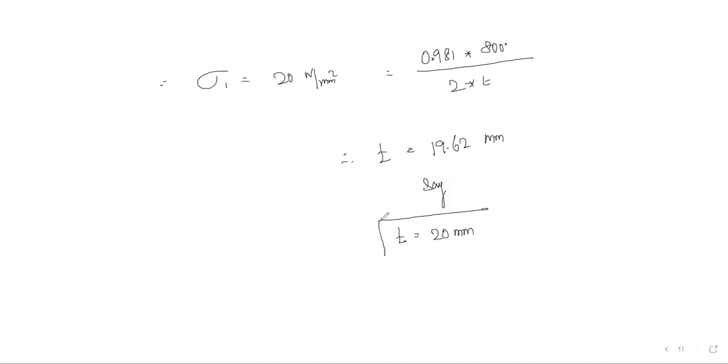So if I give 20 mm thickness, then the water main can withstand the pressure of the fluid inside the cylinder. Okay, so these are some basic problems related to thin cylinders.